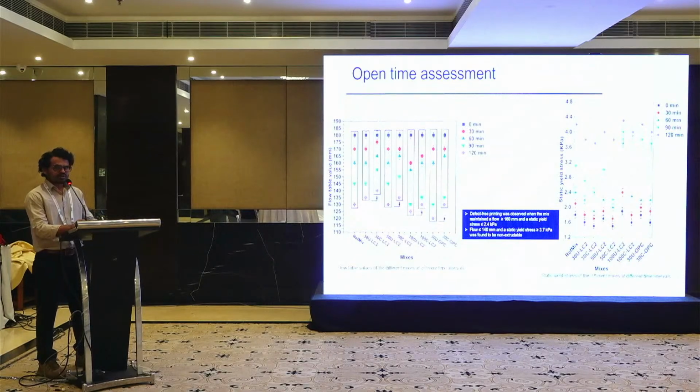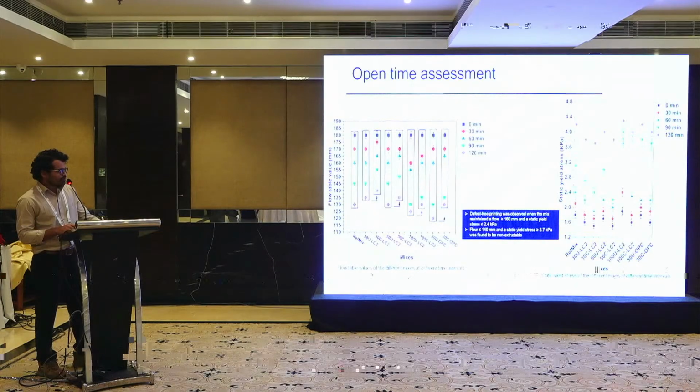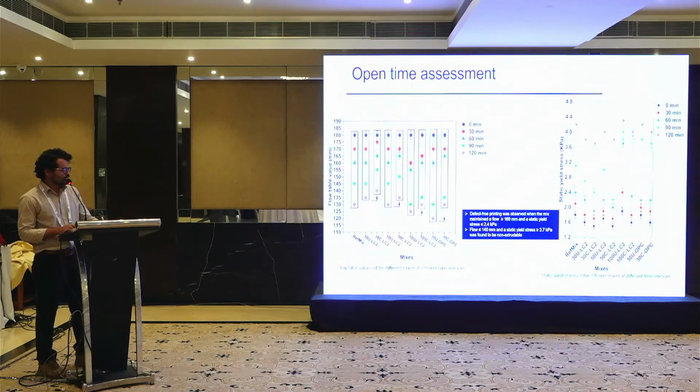Parallelly, I try to measure the flow table value and the static yield stress. Static yield stress is the minimum stress required to deform the material. What I found is the material with 160 mm flow and a yield stress of 2.4 kPa is defect free, as you see in the previous slide, and the flow value of 140 mm and yield stress greater than 3.7 kPa is found to be non-extrudable.